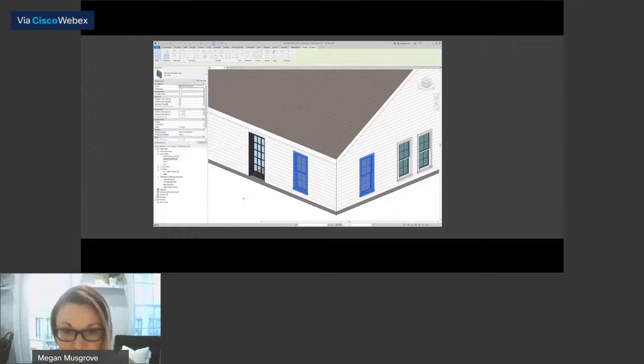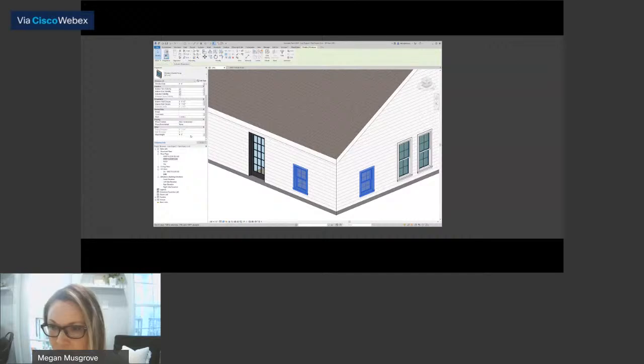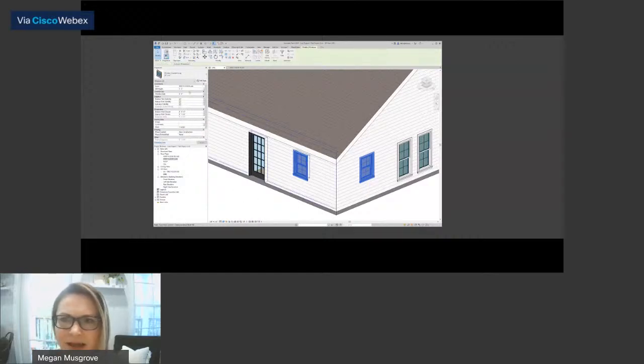3.5 feet. Now it's going to want to pull that down to the sill. We're going to go over here in our properties tab and we're going to click on that head height and we're going to do 6.8, and that's going to put those back up there. And then without having to do any math, we can look up here and see that that is a 3.2 sill height. And I like that. I'm going to leave that there.